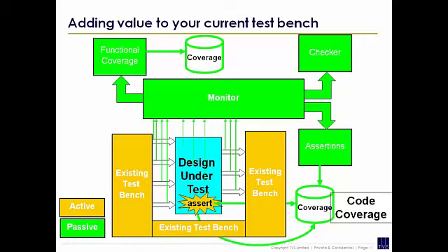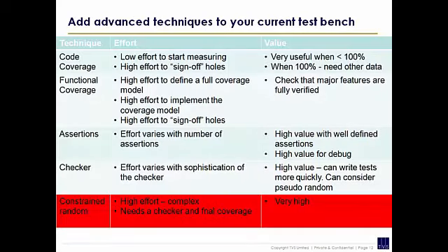So there's a double negative in there. But normally when you write a directed test, you say, I'm writing this directed test and I expect this to happen, and I'll check that it happened. But normally you should also check that nothing else happens. And that's the bit that most people don't do, because it can be a lot of checking. You've got to think of all the things that could have happened that shouldn't have happened, and you have to check that none of them happened. Checkers quite often just do that automatically for you. So you can have a lot of value just from writing a checker as well. But the assertion is the biggest, the quickest thing.